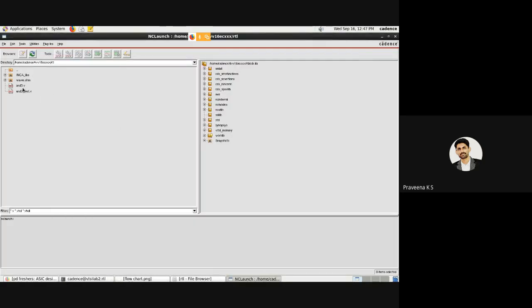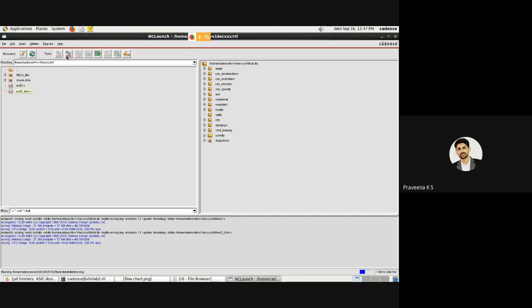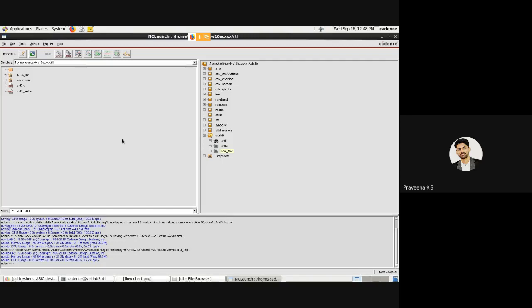Okay, so once you've done this, you have to select both: test for errors, this one, and test for errors using the Verilog compiler. Once you do this, on the right side you can see the worklib folder. Under worklib, two modules will appear, and3 and and3_test. First you have to select and3 and elaborate the design to recognize the modules, then again and3_test. Fine, once you elaborate it,